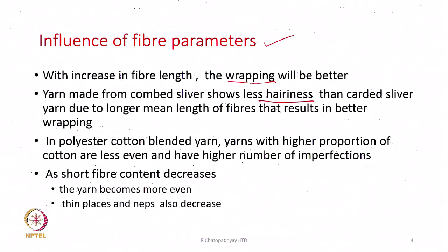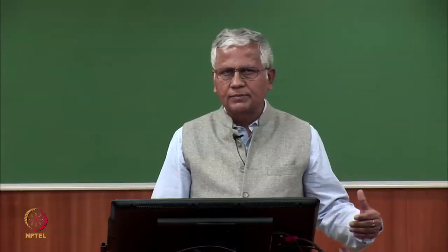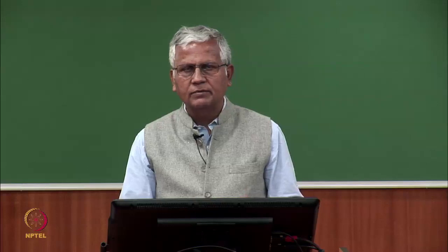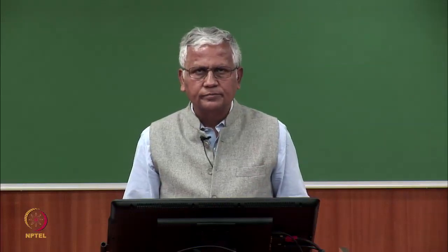At the same time, the yarn is also going to be a little stronger, because in the combed fiber most of the fibers are long and they can better wrap the core part of the yarn. So, since longer fibers will be more in number now, they can wrap better, and as a result the yarn will be stronger. The uniformity is better mainly because of the evenness, that is, the drafting system will be able to process the fibers much better because the short fibers are not there.